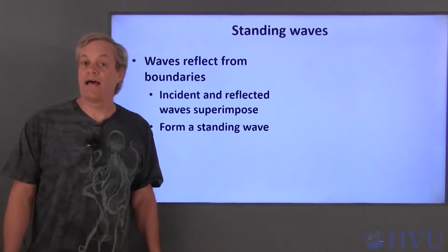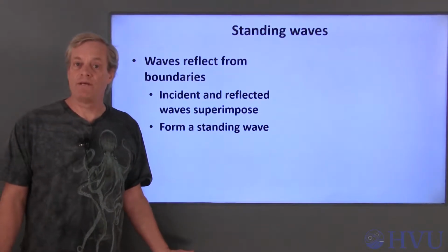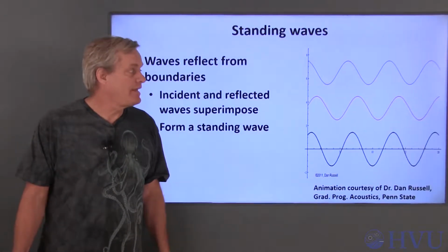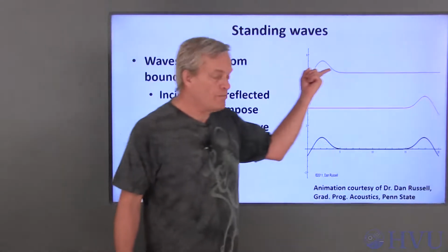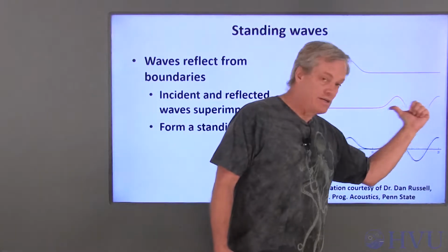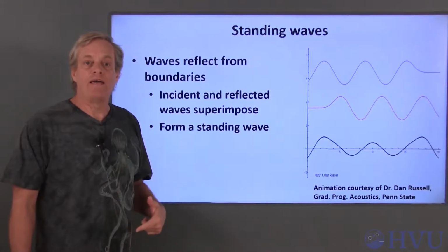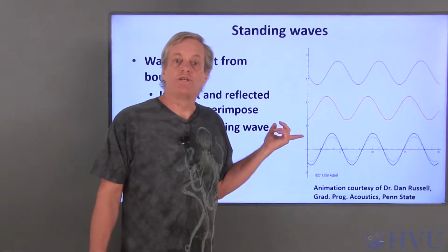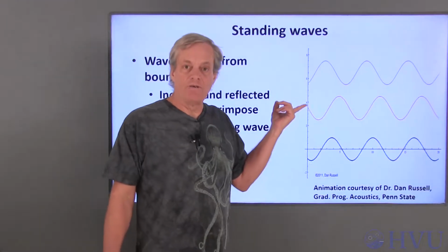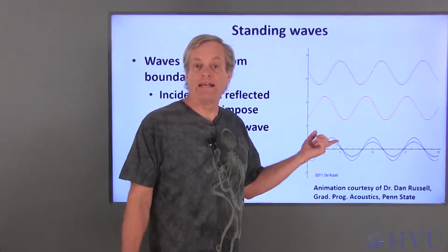In acoustics, as in vibrations, the motion of molecules is the result of waves propagating through the material. In the case of a tube full of fluid, waves produced at one end of the tube can reflect off the other end of the tube and move back towards the source. The interaction between the waves can create what is called a standing wave. This animation shows how the left and rightward traveling waves interact to form a wave that appears simply to move up and down at any given point.